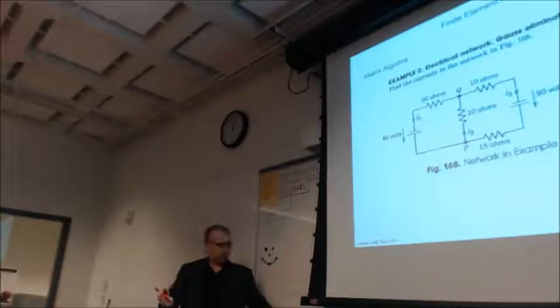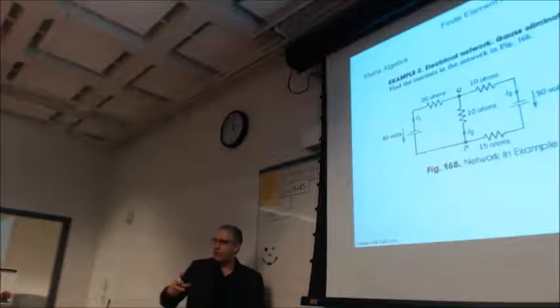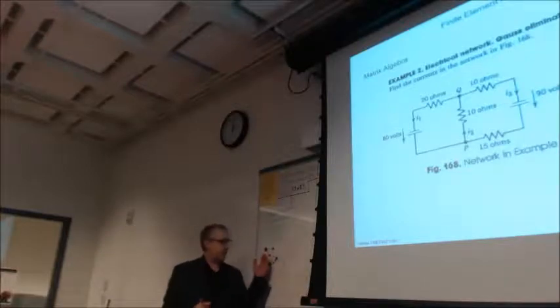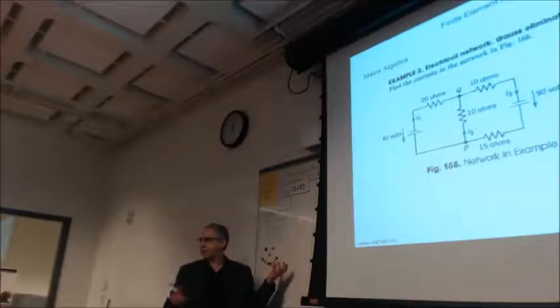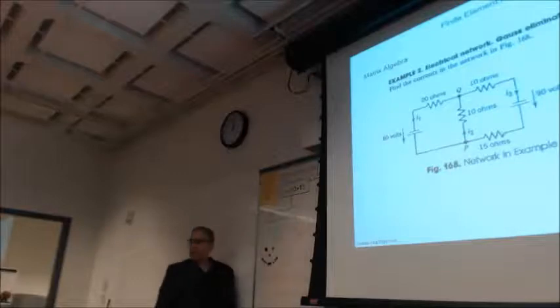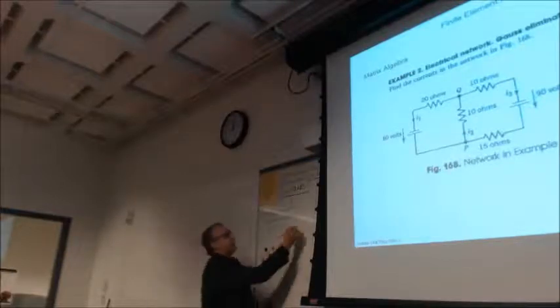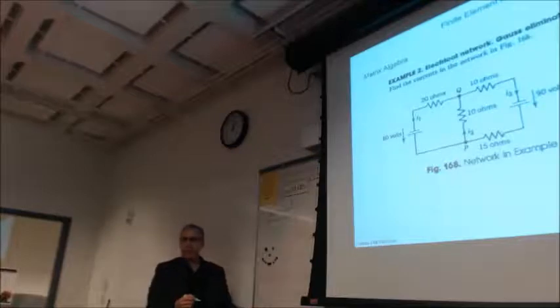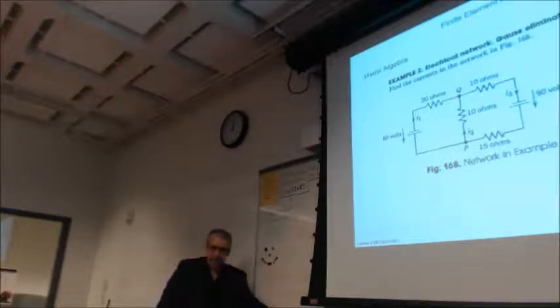When you're trying to extrude or something like that, because you know it's going to change shape, it's not elastic anymore. If it's not elastic anymore, gone. You have to have a whole other stress, strain, and something in the middle, because it's not elastic, right? It's plastic, right? This stuff only works if you have a line. That's elastic. So if you have something like this, then it's more of a power law. It's like to the N or something, right? So it just looks different. But it's still that stuff in the middle of a constitutive relation that we generate.